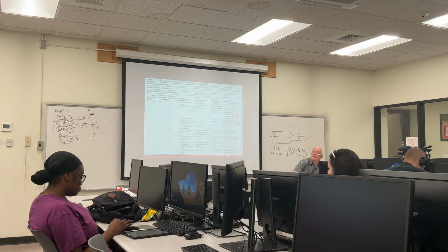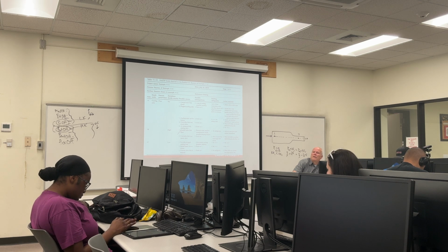That's a HAZOP. Control valve could have failed closed. That's assuming it's a fail-closed control valve. Although even if it wasn't a fail-closed control valve, you could fail it closed by the controller failing it that way. You can fail it closed or fail it open, either way. There's always something that you can do with controllers.